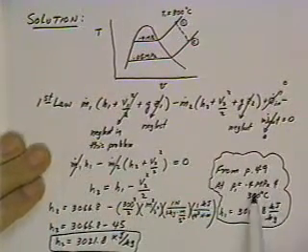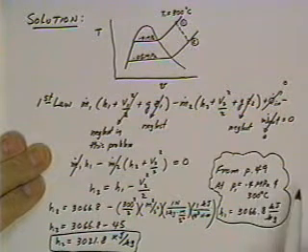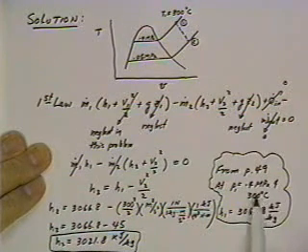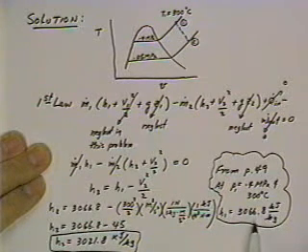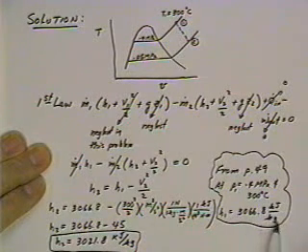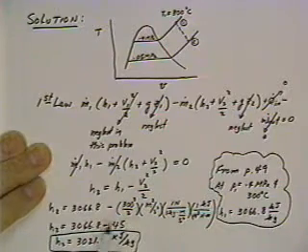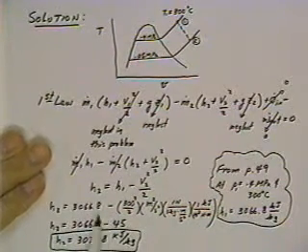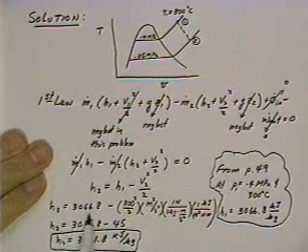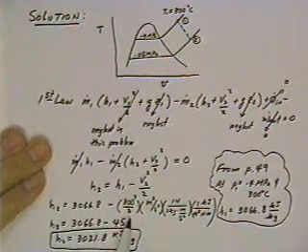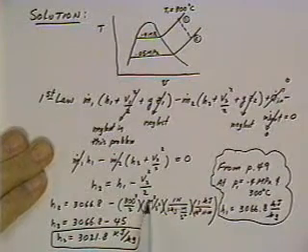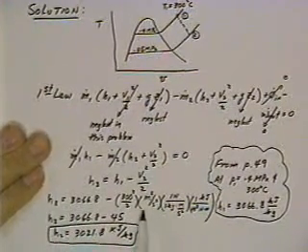Okay, so we just looked up on page 49 from the steam tables at 0.4 of a megapascal and 300 degrees C, we find enthalpy of 1 is 3066.8 kilojoules per kilogram. So we plug this back into our equation, and the enthalpy of 2 is 3066.8 minus 300 squared over 2 is the kinetic energy term. And I filled in all the units here for you.